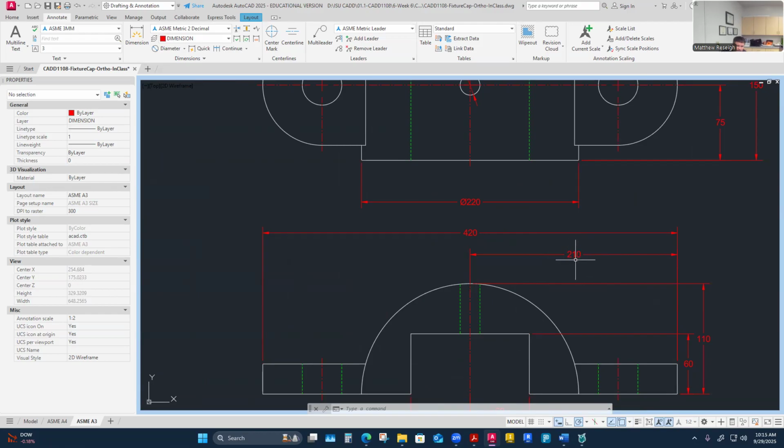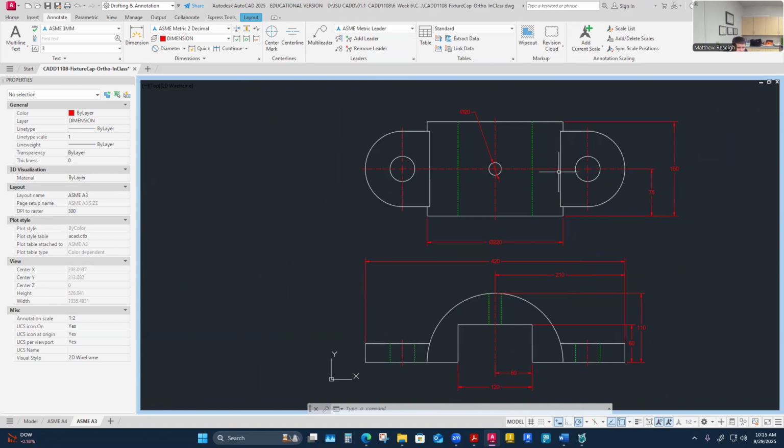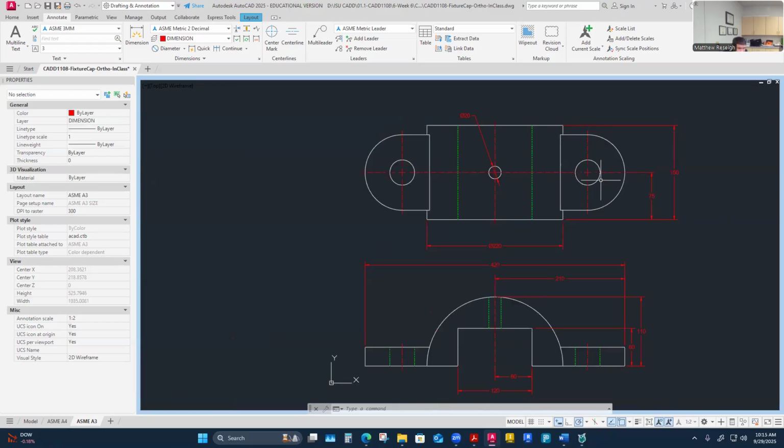However, I told you that in my mind, I'm actually viewing the datum as the center line, and I'm calling 210 out to the edge from center. So I'm viewing this dimension not coming from right to center, but from center to the right, if that makes sense. It's a weird thought process that I'm trying to get you to develop, and it will make more sense when we talk about GD&T controls. I'm softening the blow of how horrible that is to think about as I introduce it in every project, because it helps me determine size and location. But long story short, I think I'm good to move on from the size and location of that little hole. Now let's move to the ears themselves.